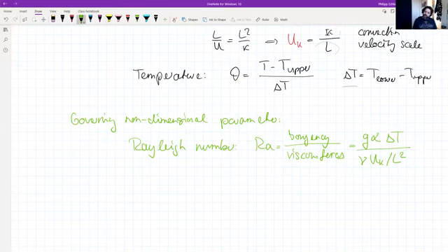The realization that there needs to be a certain temperature difference for the whole thing to come into play means, if you translate it to the non-dimensional Rayleigh number, that there is most probably some critical Rayleigh number that is needed to start the whole process. It's easy to understand: the temperature difference matters, but of course the gravitational acceleration also plays a role.